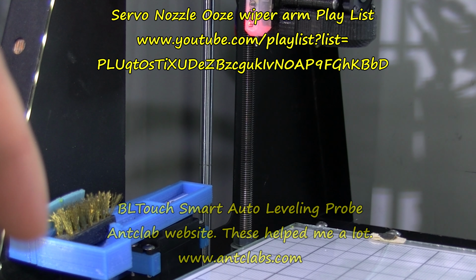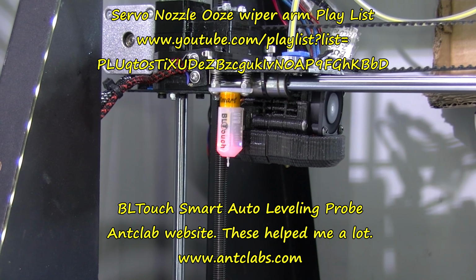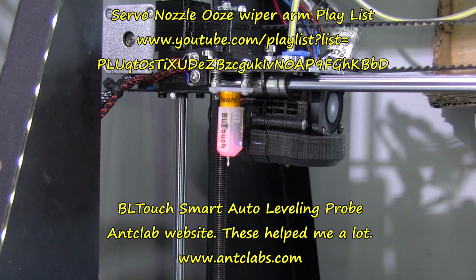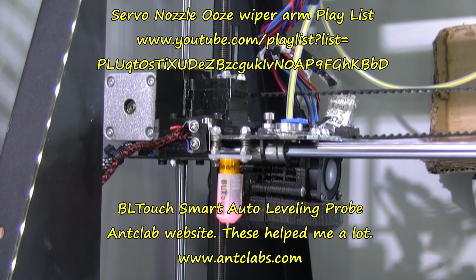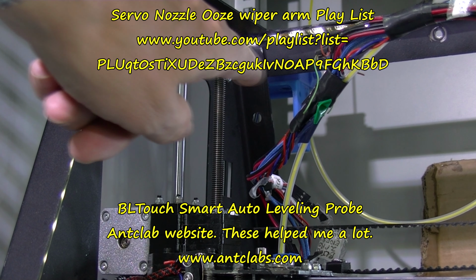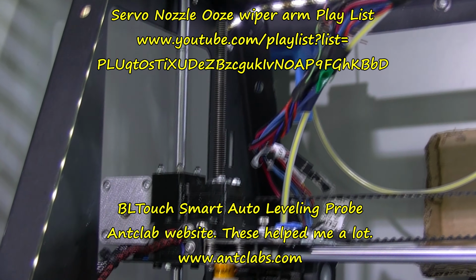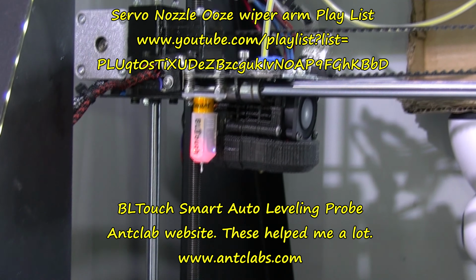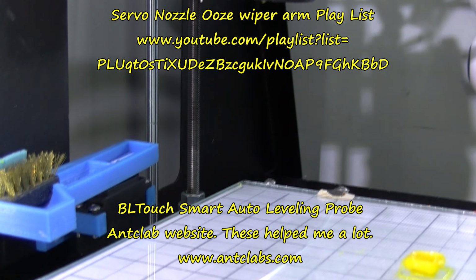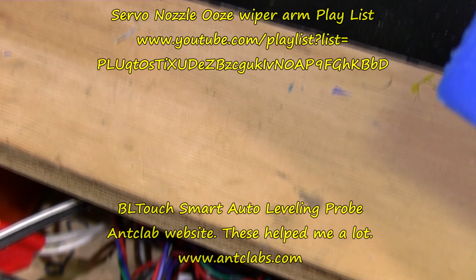So that's powered off the same circuit. The BL touch there, which gets a big thumbs up, that's powered off the same circuit, and I have a filament run out sensor. Don't know if you can see it from here. It's this blue sort of thing up here. The filament goes through there, and knocks a micro switch if the filament is feeding okay. All those are powered into that same port on this RAMPS board down here.